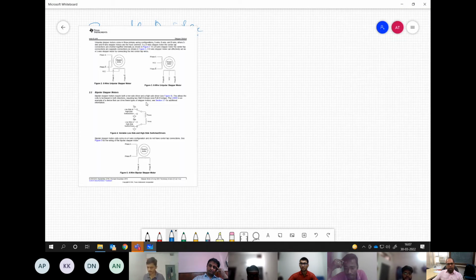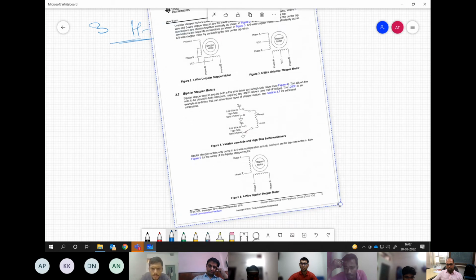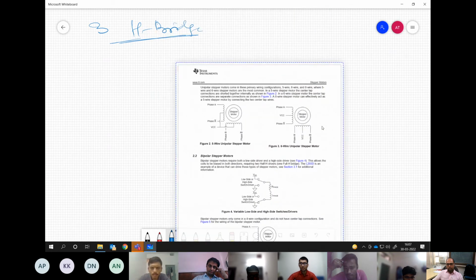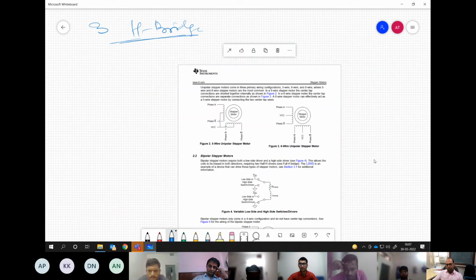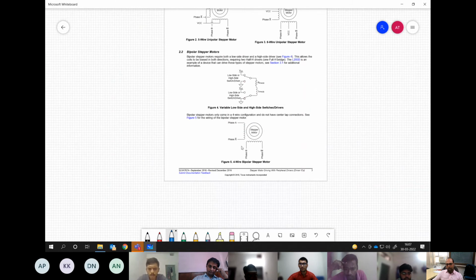They have this kind of application of voltage across the coils. Sometimes they may have 3 terminals. One they will connect to the supply, the other 2 they will keep toggling, or they may have a simple A dash B dash kind of connection. These are done basically to ensure that you have a slow or fast decay arrangement. Understanding my point?